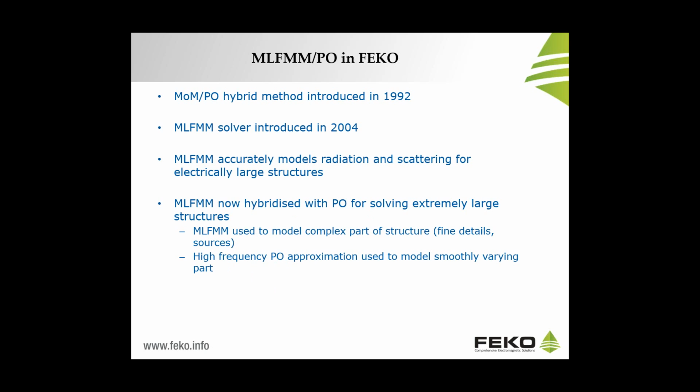Also in FEKO, we have the large element physical optics method. This is an alternative set of basis functions which allows us to have mesh sizes of multiple wavelengths. This leads to dramatic computational cost savings relative to the standard PO. And as you will see in the next slides, we have also implemented the hybridization of MLFMM with large element PO.